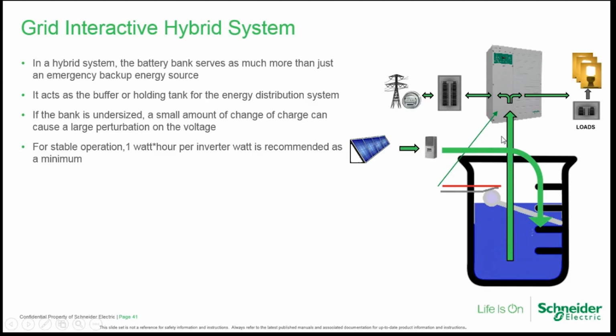like that. For stable operation, we're going to recommend about 1 watt-hour per inverter watt as the minimum to stabilize the system. Don't undersize the battery bank. Even though you think that your main use is just for self-consumption or export, don't undersize your battery bank.